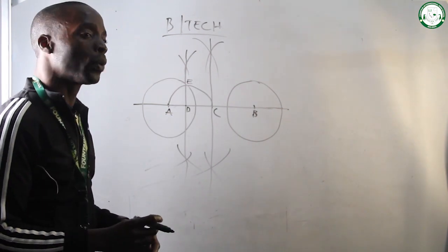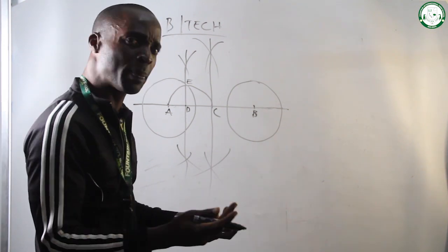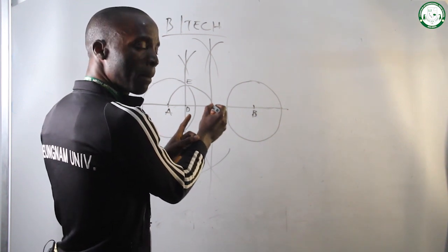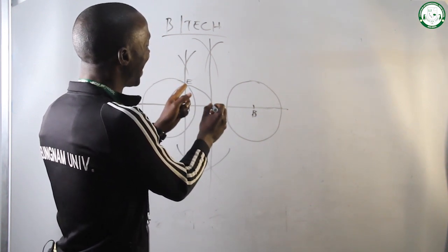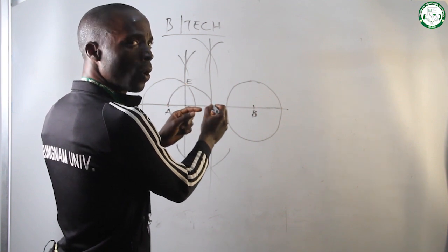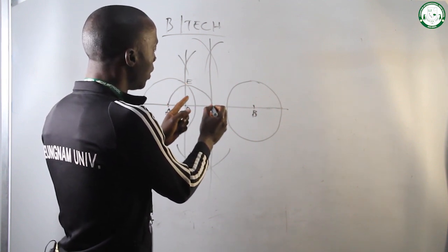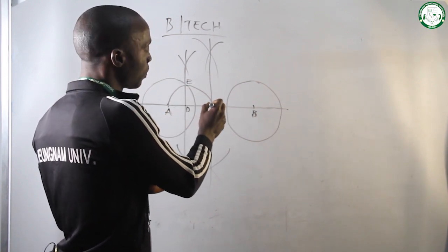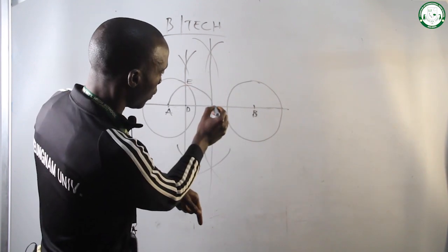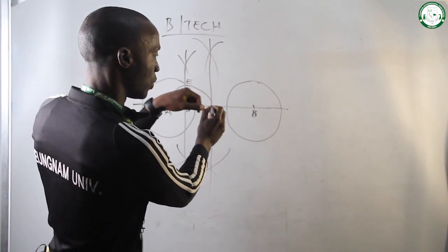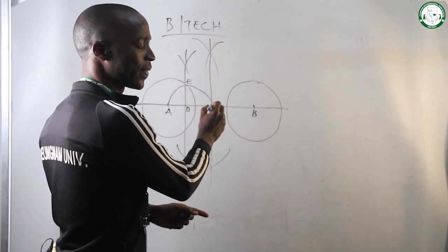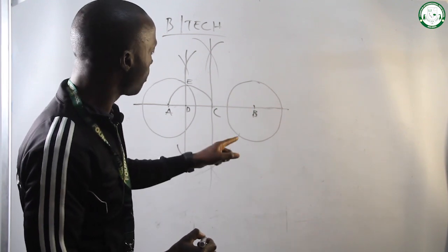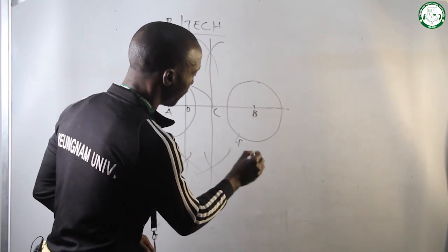Okay? Now you can take your compass again, or maybe your divider, and measure out this line. Put the pin of your compass here with center C. Measure out this line, EC or CE. It must not be more, it must not be less. Once you have measured it out, now take it downwards. Swing your pencil downwards towards the circle with center B and cut an arc on it. That point is your point F.